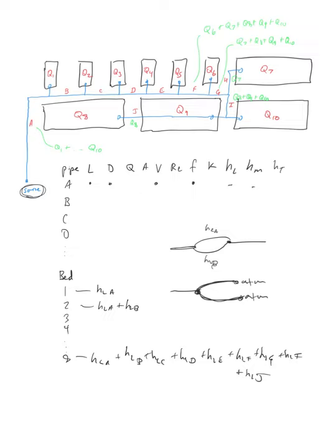Now, you're not going to purposefully, for example, some people have done this in the past, say, hey, Q1 needs more head loss, so instead of this being a direct connection here, let's make this pipeline go like this, so we get more head loss through there. Not a good idea. It adds cost, adds complexity, it's silly, right? A better way of doing that is just adding a valve to that outlet so you could throttle it down if you wanted to.